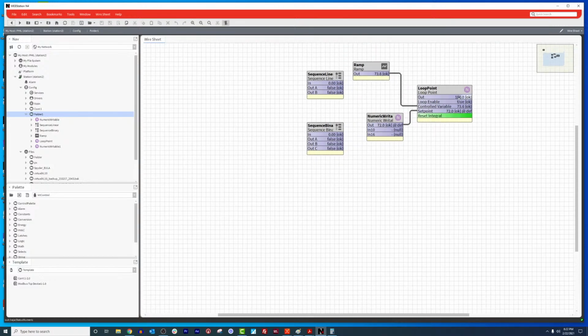I mean, it's at 100%. And look, it's at 100% even though I'm going down. This is what's called windup. You hear this concept of windup, and windup is where you have all this integral buildup. And remember, the only point at which we can start to decrease integral is when we drop below. Watch what happens now. See it starting to decrease? That is all that integral going bye-bye.